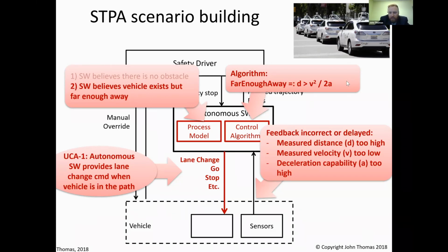We have carefully analyzed and already thought of these cases where the sensor can fail and the sensor can report something dangerous. So at least for the first 2 bullet points, those come directly from a sensor within tolerance. We compare lots of different sensor data and make sure that they're within tolerance and they all agree. Otherwise, we go into a safe state. But that's for the first 2 bullet points anyway.